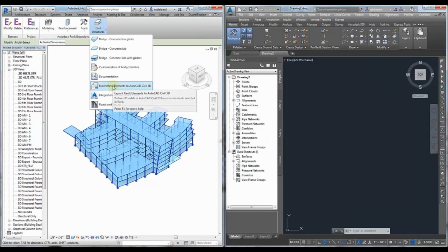and allows both architects, structural engineers, and civil engineers to be able to very quickly send the model to the civil engineer, and then make sure that everybody is coordinated as far as the origin point of the file. I'd rather not use shared coordinates when possible. There's no reason really to not be able to set the origin of the file at the beginning of the project and avoid the shared coordinates headache.